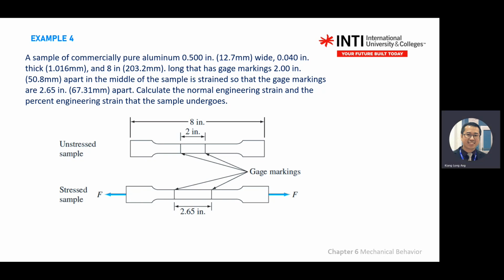So what is the answer? It asks you strain. What do you take? How many change the length? Again, what you're focusing on? You're focusing on the gauge length, not the total length, not this 8-inch thing.